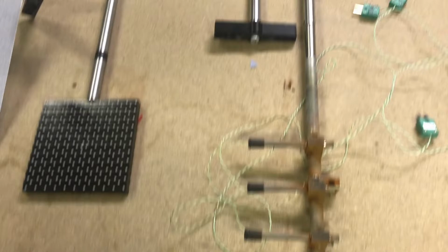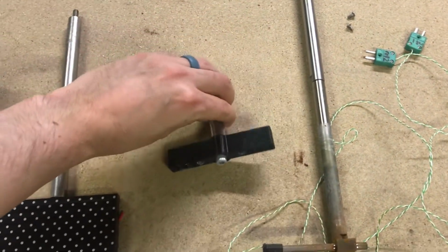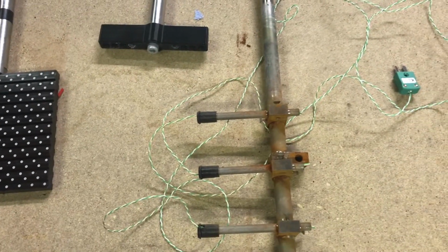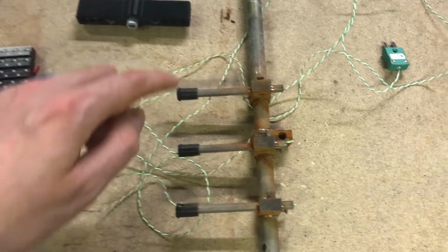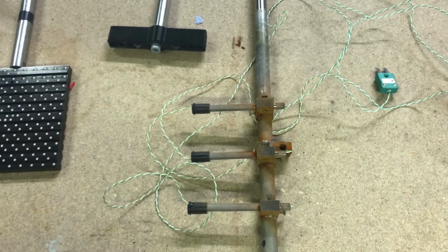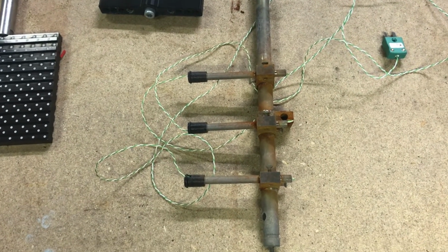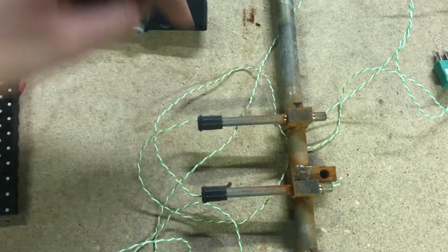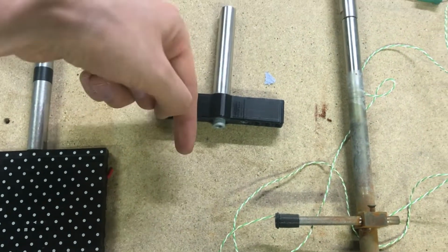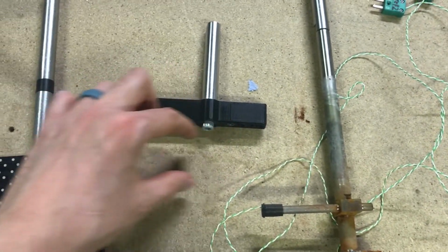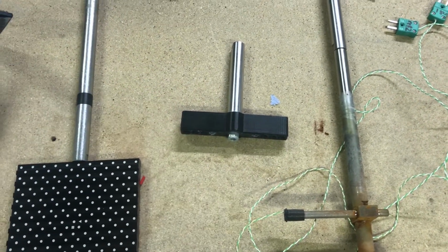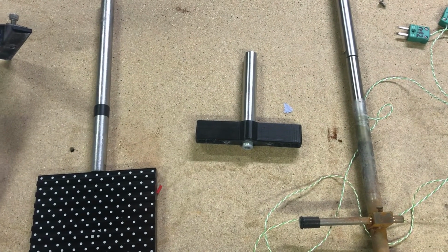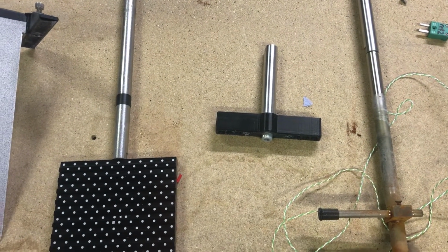And finally, I've got 2 things here which I use to hold thermocouples, so the green bits are the thermocouples, and this is to perform some calibration for the temperature measurements of the surface. And similarly, these parts, they're actually metal straws, can be inserted into here to perform calibration of a fluid in an area here. And that was actually useful for a different technique called laser-induced fluorescence, or LIF.